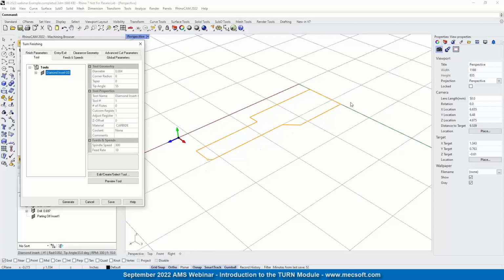And if you have your stock set to 0, then in effect, if you think about milling, if you have a stock of 0, the tool matches the actual part surface. So you could have done a roughing and a finishing in the roughing operation itself just by adding the cleanup pass. But we're going to go ahead and do a second operation with probably a new insert, and we're going to do a finishing operation.